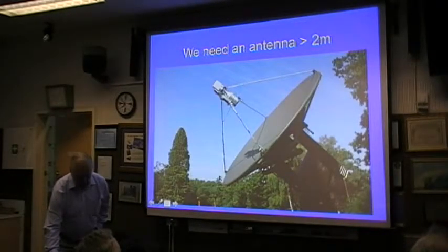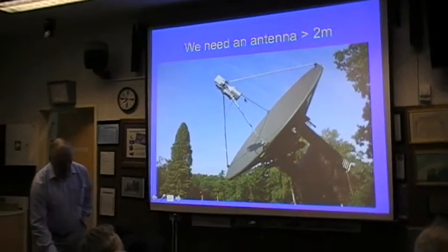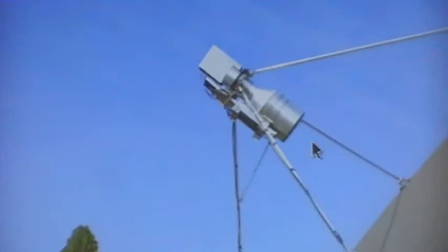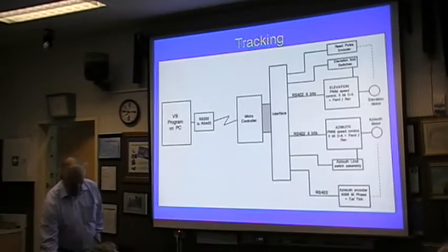So there's the feed. It's basically dual mode. It's a fairly standard dual mode feed, but it's not circularly polarized. There's no need for that. It's linearly polarized. The down converter's out on the dish, and it's under illuminating the dish.